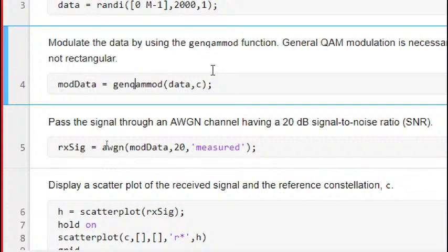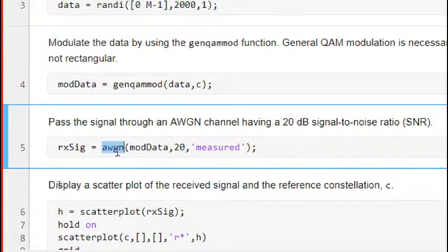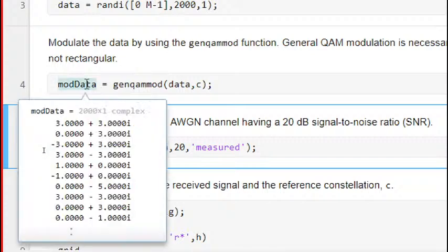Okay, now further we are going to define an AWGN channel. To design an AWGN channel, there is an inbuilt function in MATLAB, or if you have a mathematical equation, you can design that equation also. Better to use the inbuilt function. Why are you going to design it again? Use this, and here this is the modulated data, which will be complex data, right?